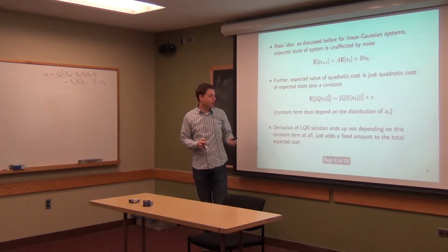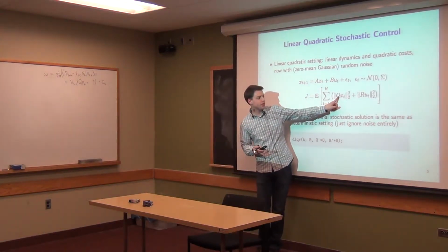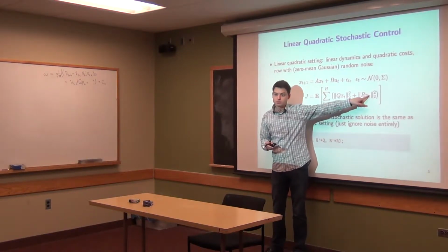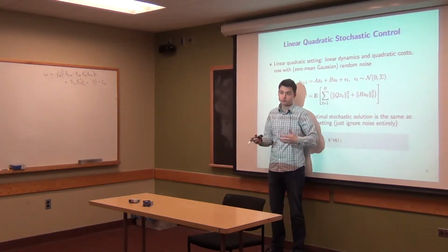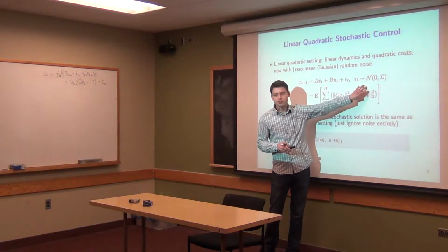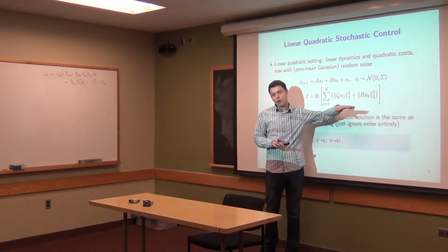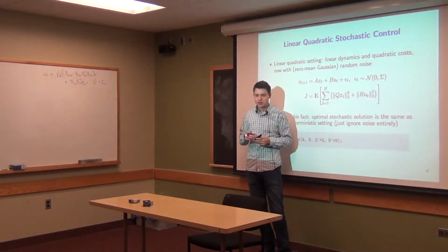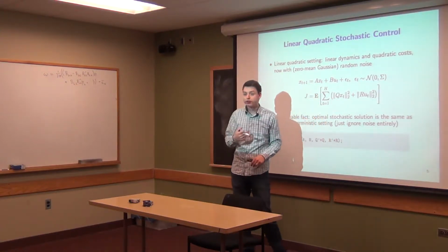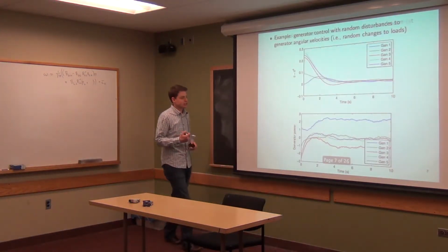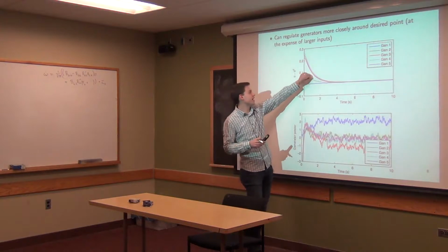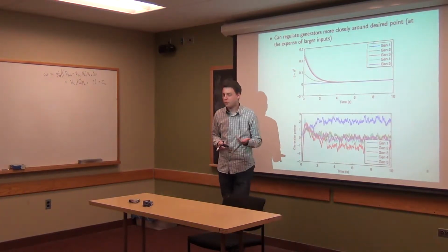So remember, LQR has this cost where we penalize both the deviation from the 0 state and deviation from the 0 control, which could either be actually 0 or they could be the desired control in the desired state. And if you decrease the penalty on the controls, what will end up happening is you get bigger entries in that K matrix, and you'll be more aggressive about applying control to account for errors. And so what happens is it looks like this. Now all of a sudden, it looks in this graph like you're doing it better. You also converge faster because you're using really big control inputs there. That was the problem, remember, also from last time.